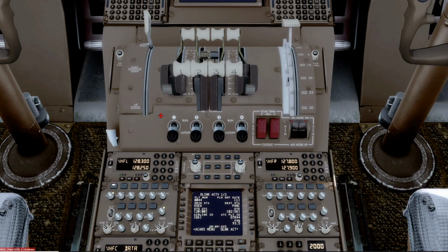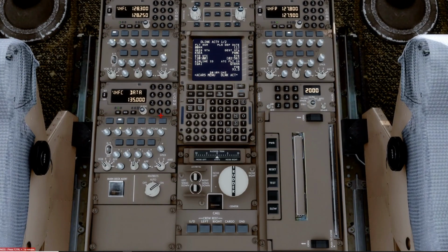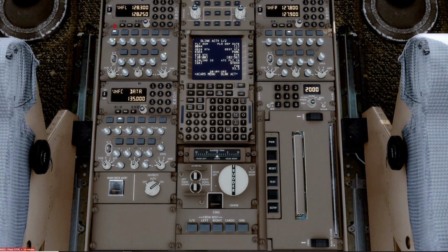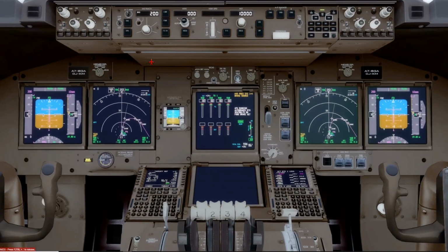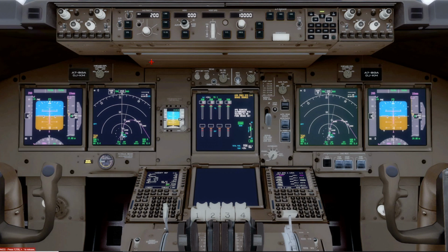And then I'll come down to the lower panel and check my audio control panel as desired. And then if I wanted to, I could check rudder and aileron trim 0. That's something I would probably do. And then adjust my seat and adjust my rudder pedals. And then we're done with the cockpit setup at that time. Then we get the ATIS, and we get the clearance.